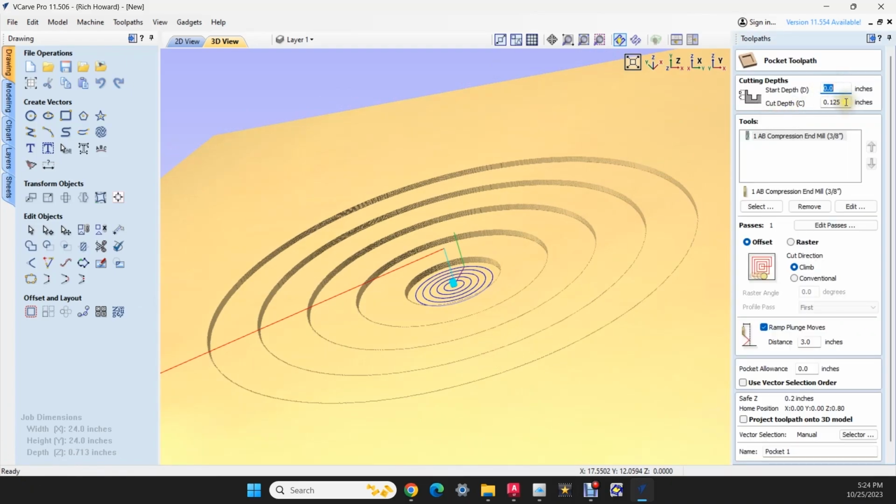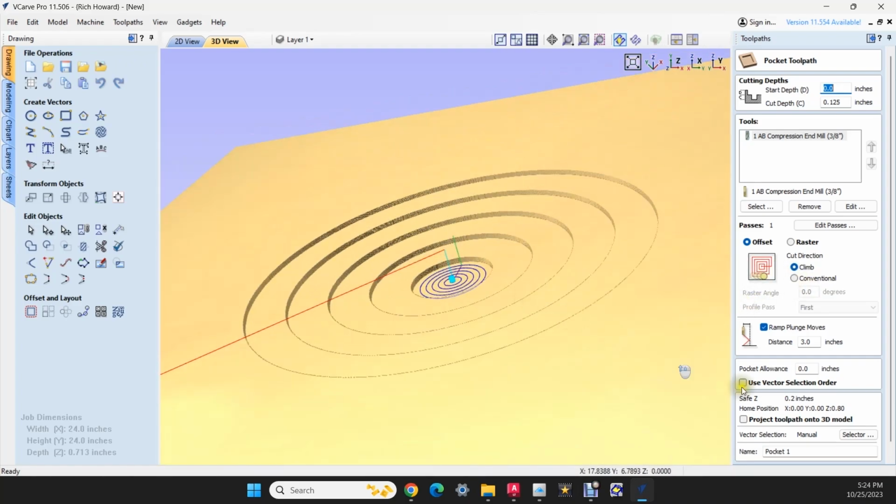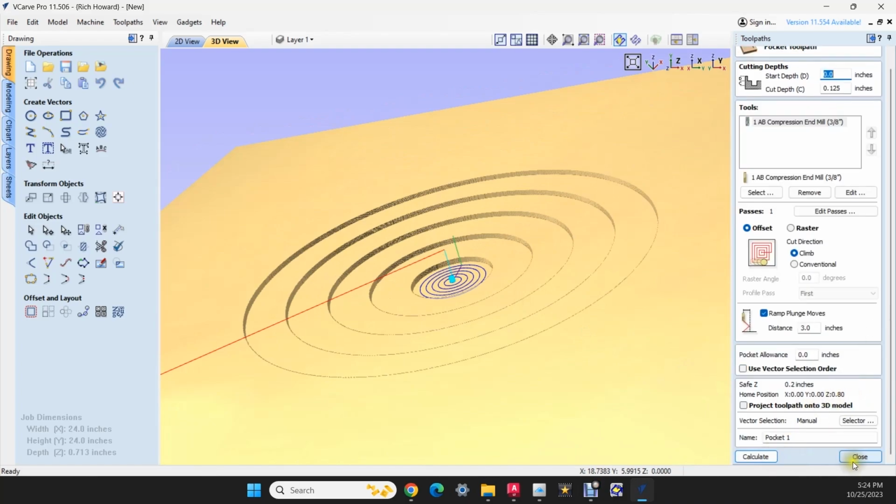Where are you starting and what is your cut depth? What I've learned is you have to understand where you are actually starting. And once you know where you're starting, I think you'll be able to make these tool paths at the proper depth, so you're not wasting time cutting air for no reason when you don't intend to air cut.